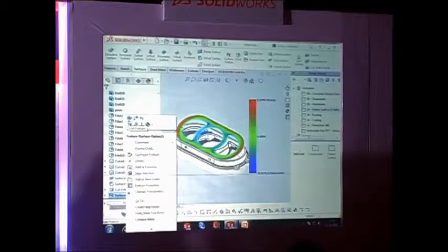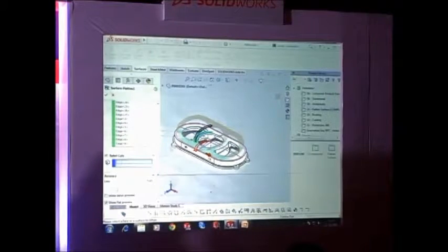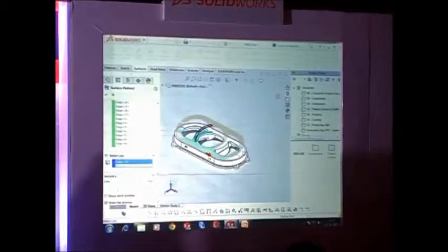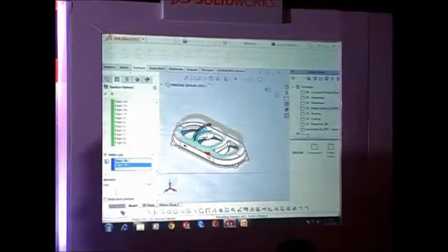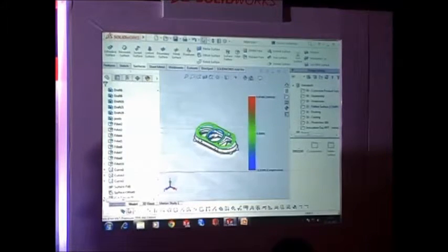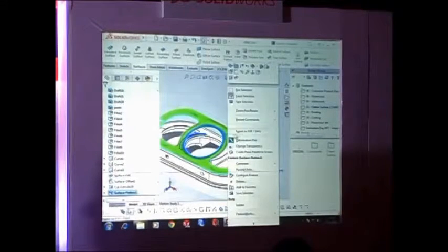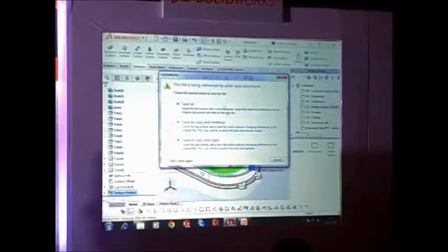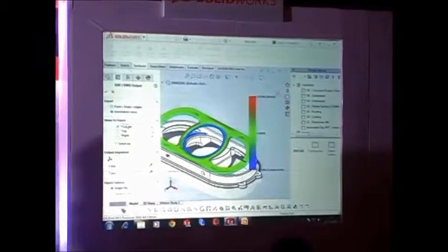To relieve this stress, SOLIDWORKS 2016 introduced a new feature known as relief cuts on the flattened surfaces. By simply selecting an entire line, these induced stresses are relieved. At any time, this can be exported into a DWG or DXF format for NC manufacturing. So we can export even in the current position.